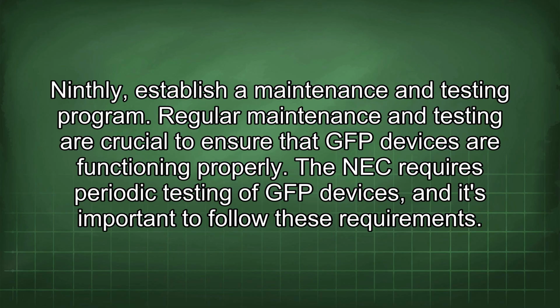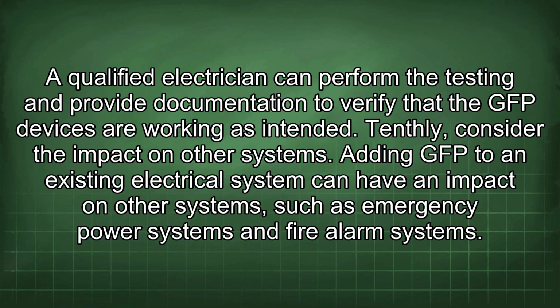Ninthly, establish a maintenance and testing program. Regular maintenance and testing are crucial to ensure that GFP devices are functioning properly. The NEC requires periodic testing of GFP devices, and it's important to follow these requirements. A qualified electrician can perform the testing and provide documentation to verify that the GFP devices are working as intended.